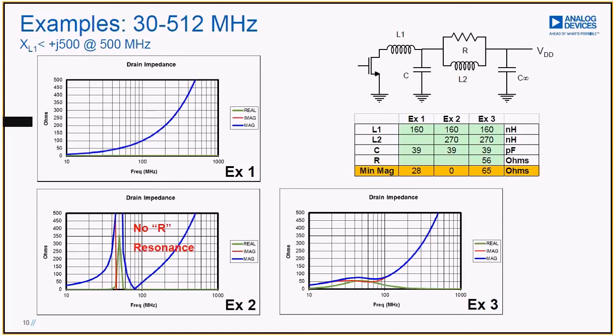And of course, the problem we find is that if we make it small enough so that it's not resonant at 500 megahertz, then it's not big enough to provide any kind of isolation at 30 megahertz. So this is the classic problem. We want an inductor that's both big and small, too big and too small. And we worry about any time an inductor impedance, especially an air-wound kind of inductor, if you see the j omega L getting in that 500 ohms to 1,000 ohms range, you're probably above self-resonance. So we have to keep self-resonance of the bias components in mind all the time.